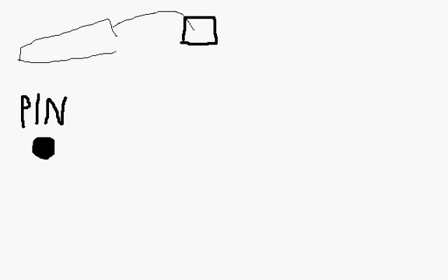And this big black dot is the actual pin. Actually, it's not the actual pin, I guess. It connects to the pin. I mean, internally it's a pad. It's a square of conducting metal inside the chip package, and then there's a very fine bond wire that actually connects it to the actual huge pin that's on the outside of the package like that. You won't see that on the diagram, of course, but basically you can think of it as being the pin because it connects directly to the pin. So electrically, for all intents and purposes, it basically is the external pin of the data bus.